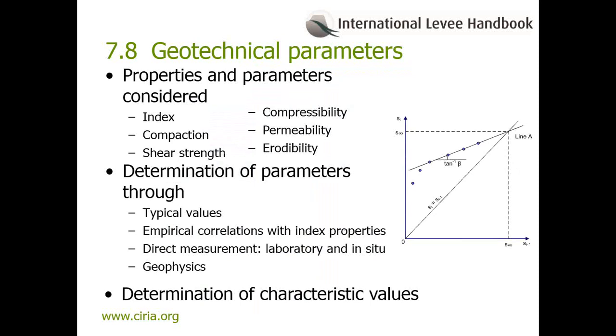While soil classification is not considered in these slides, it is worth stating that one of the main takeaway conclusions of the section dealing with soil classification was that there are differences in the various systems used around the world and historically within one country. Therefore, when dealing with third-party or old data, it is important to be clear what system has been used.